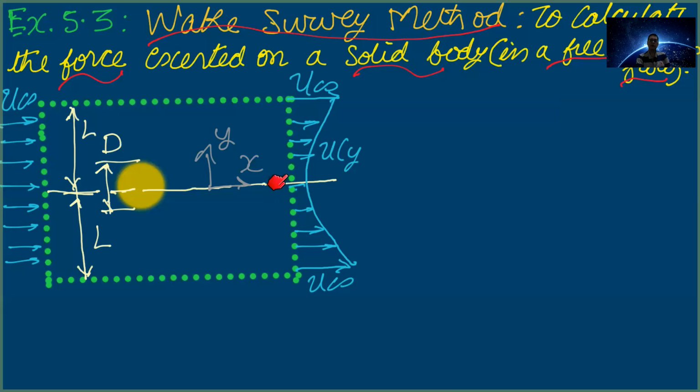In integral form, at this point, mass flow rate is integral of rho u as a function of y dy. Okay, so basically we do an integral with respect to, in this case we are considering the surface area, this is a 2D problem where the dimension perpendicular to this plane we are taking as unity.